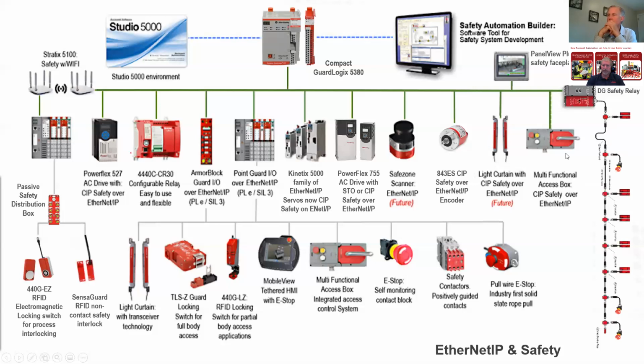So that's just a very quick, high-level mapping of many of the CIP safety solutions and many of the contemporary product solutions. There is not a product on here other than this e-stop and this contactor. Nothing else on here is electromechanical in nature whatsoever. Everything here is solid state. And that's one of the things that we keyed in on early in our discussion, this old way versus new way, conventional versus contemporary. These are the contemporary switches, devices that we want to focus on.